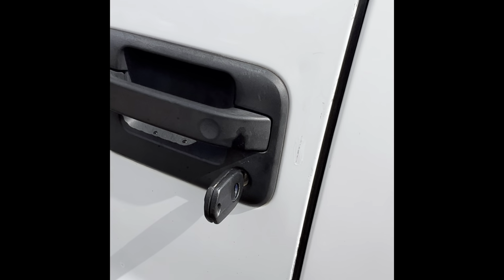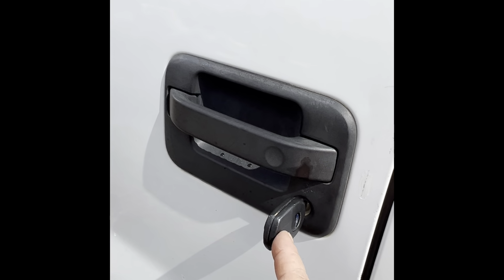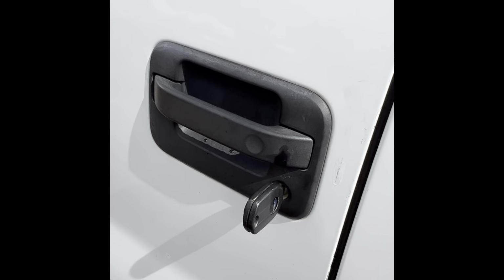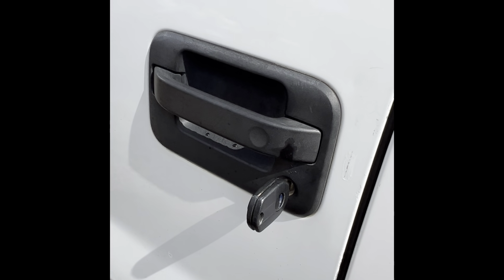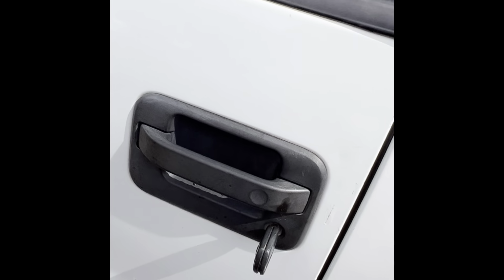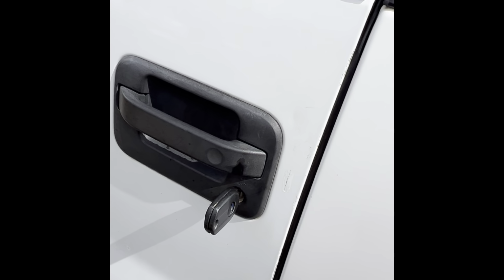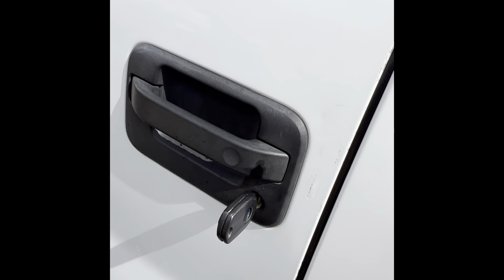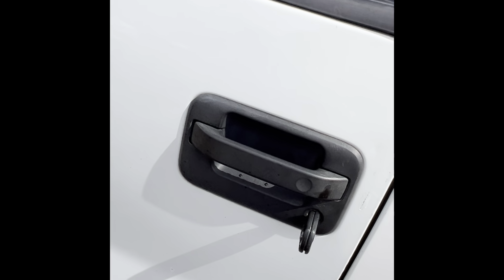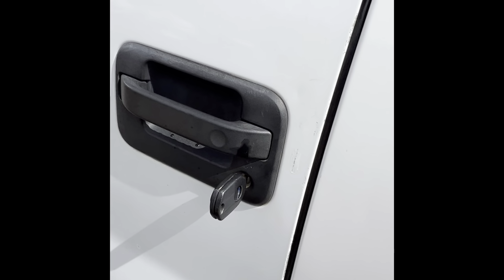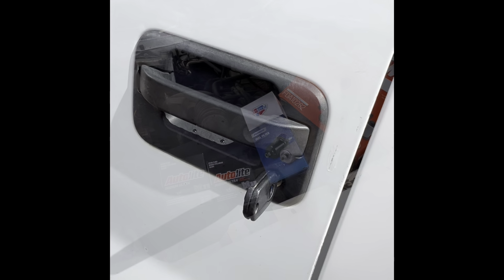Tip number 1, it's a good idea to get in a good habit of leaving your key stuck in the door when you're working on anything with electric windows and locks. I have seen people lock them inside, and I've done it myself. Working on the vehicle, alarm goes off or something. It's just better to have them out here, and then you know right where they're at.